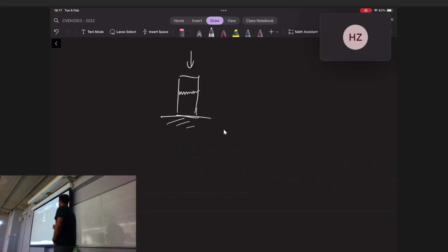It happens only at one point. So, how do we calculate the strength of that? Really simple. Again, you look at the cross section area multiplied by the yielding strength of steel. In fact, it's the same formula as yielding on the cross section, because yielding, by the way, can happen both ways. You can stretch a piece of steel and yield it. You can squish a piece of steel and also yield it. Yielding is just an instability of the material. So that's section level failure. The key characteristic about that is it's only one section. So it's a local failure.